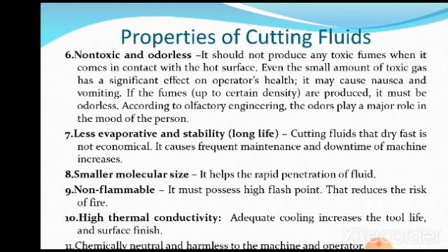Non-inflammable, it should not burn. Non-inflammable means what? It should not be subjected to any burning. For that purpose, it must possess a high flash point that reduces the risk of fire. It should not catch fire while it is cooling the cutting tool and the workpiece.